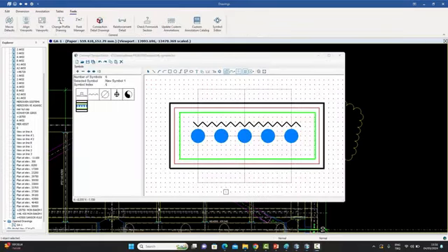One last thing I would like to mention is that, as I said in the beginning, there's a boundary over here inside which you need to create your symbol, but it does not stop you from creating a symbol which goes outside this boundary, as you're seeing on your screen right now. It'll basically just take the whole thing and draw it when you actually insert it in your file. The central box will only be used for locating the origins of the symbol. So you could have a long rectangle if you wanted to, a vertical one or a horizontal one or some other shape. It doesn't necessarily have to stay within the boundaries of the square which is provided.